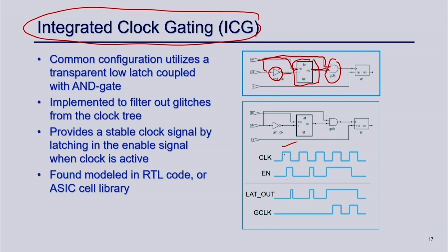So, since this is clock 1 and this is the negation of the clock, there is a glitch here, right, you can see here. For this part, this is clock 1, that means clock bar is 0. So, that will not be propagated to the latch out, but this part will be propagated, right. This is the latch part. This will come at the latch out at this point, but at this point clock is 0, right. So, this glitch will not be propagated out at this point.